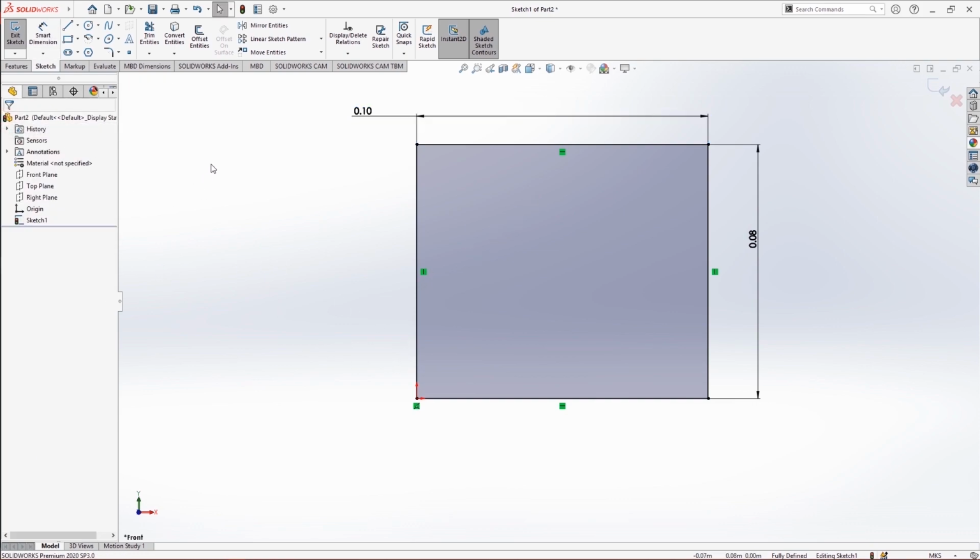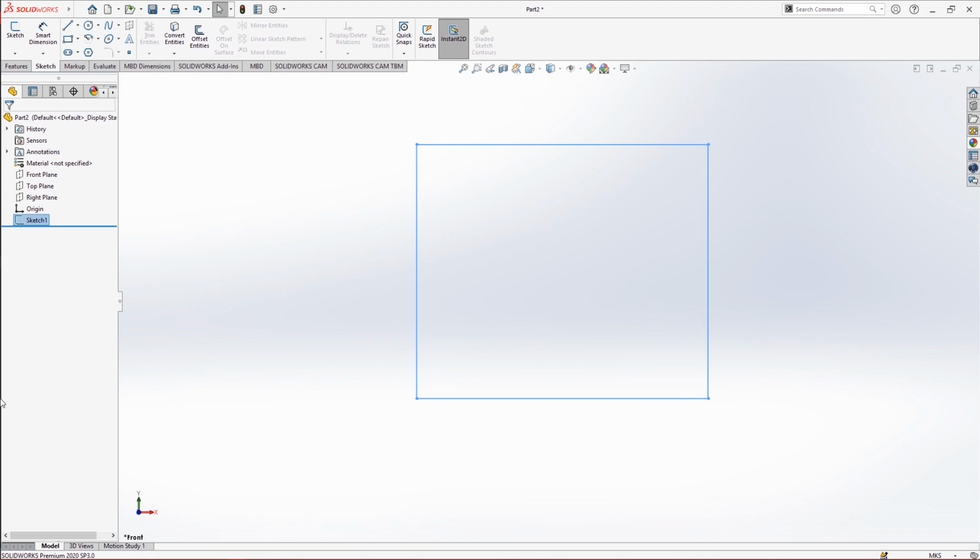The next part is let's go into the 3D. To go into the 3D, you have two options. Either you just get out of the sketch mode using this one. Okay, let's just do it. Now one more thing about the feature manager tree, this particular handle: you can choose what you want to see and what you don't. You can just keep it down and you can see the sketch, and if you want to go back, you can just put it above. So this is how it's done.